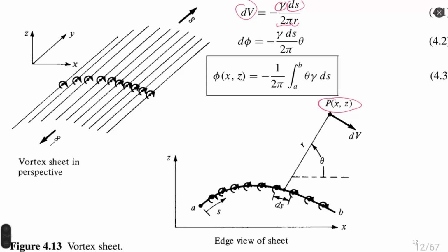It's not important how big the strength of this vortex is, or how big the size of this sheet of vortexes is, the change of velocity will be 0, and it guarantees to us that on the external wall of the calculation, or at infinite distance from the airfoil, the velocity will continue to be the undisturbed infinite velocity.